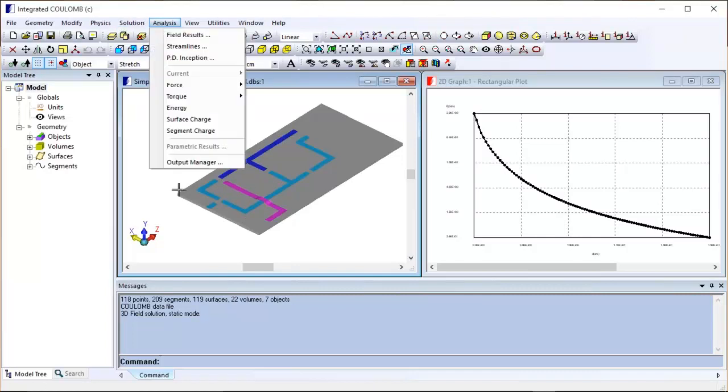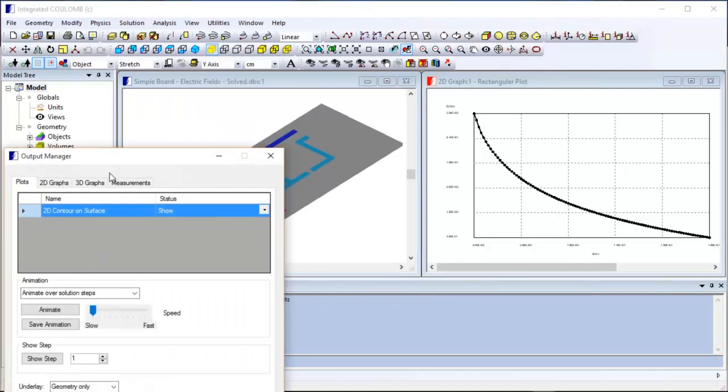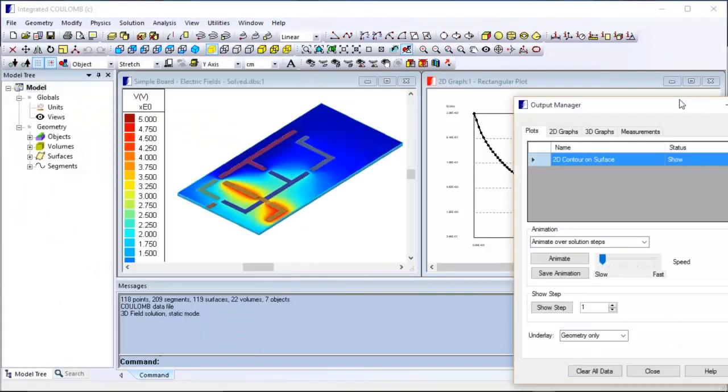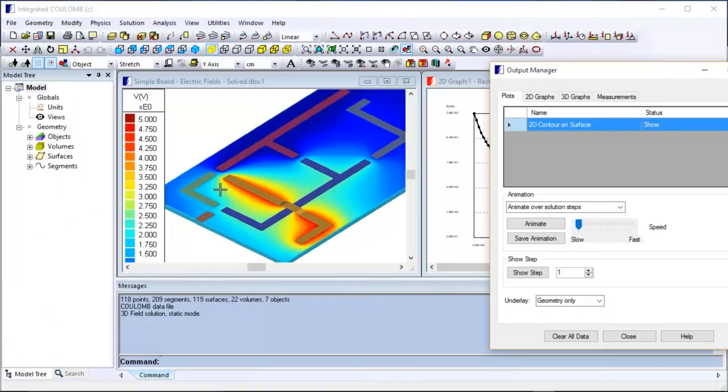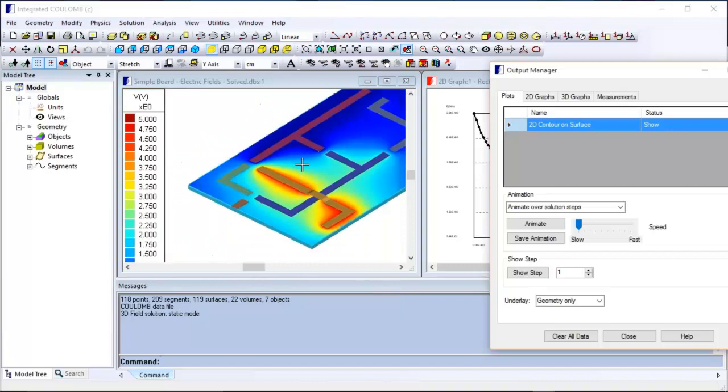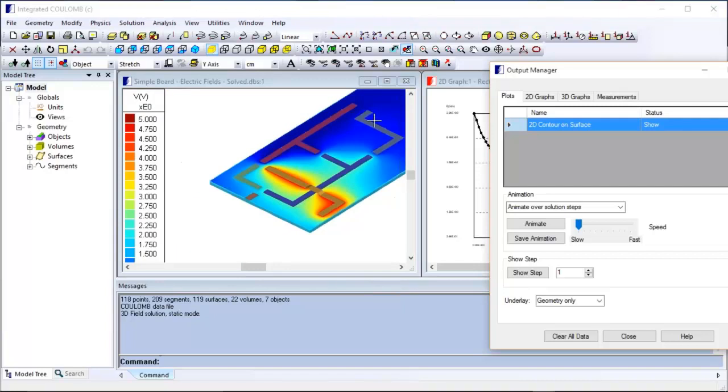So they will simply float to whatever voltage they float to. And so if we return to the contour plot that I was showing initially, then you will see that indeed if we look around any one of these, here's the 5 volts around this strip line. This one is achieving a kind of blue-green color around the 1.7 volt range, and so on. They have all floated to different values, this one being much closer to, let's say, 1 volt.